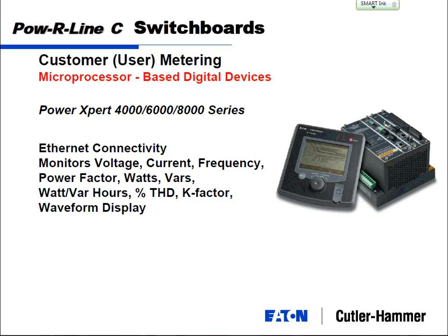And in the case where you have a fault that occurs, your circuit breaker tripped, you're trying to go back and look at what happened, you can pull up that fault condition, pull up 30 cycles before and 30 cycles after your tripping event, and you can literally look at the waveform, see what happened, see when it spiked, see when it tripped, and see when it turned off.